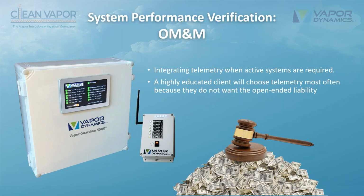A lot of times what we'll do is put telemetry on this. There are some states that want to see pressure probe data, being the pressure differential data, monthly. It just doesn't make sense to go to a building where there are maybe 30 to 50 probes below the slab and get data from every one every month. It's not going to happen. So you put it on telemetry. And the cool thing about telemetry is there's hour by hour documentation of how it functioned.